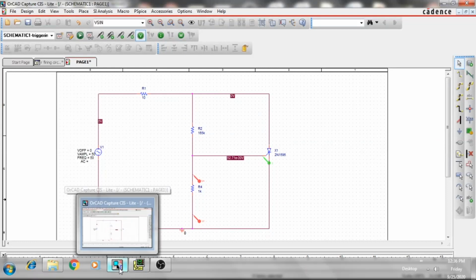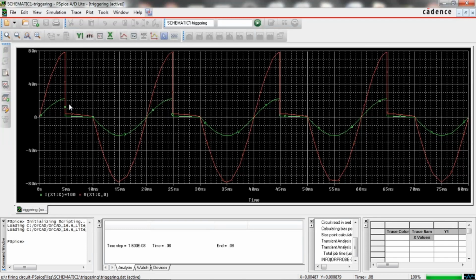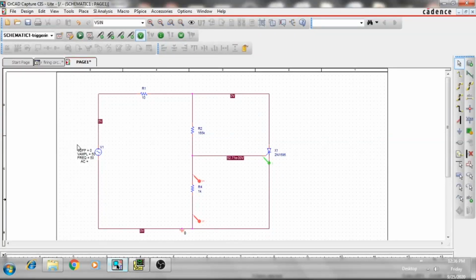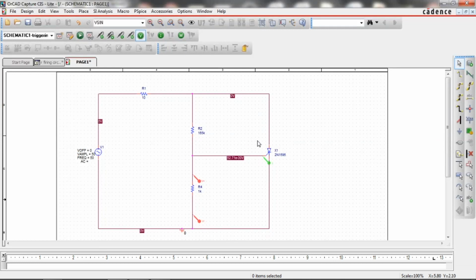This we are observing here. No voltage, it is zero, and no current. But in the negative cycle, what happens? When the input voltage goes negative, this will turn off because J1 and J3 will be reverse biased and J2 will be forward biased. Once this is turned off, the entire current moves in this direction. So again, that's the reason you will find negative voltages and a negative current in this direction.